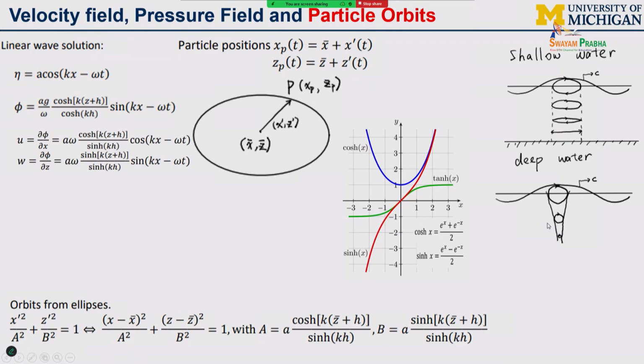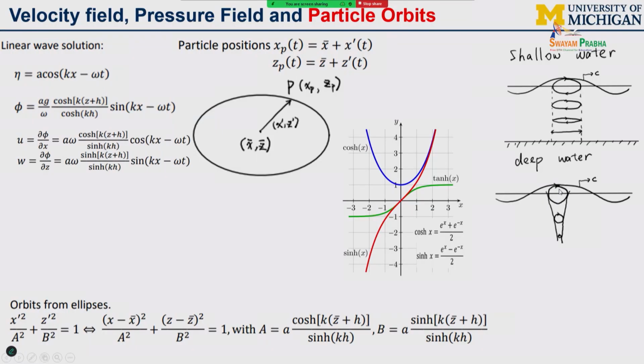Okay, when we say 5%, 23%, it means, okay, this particle motion, and at the surface, let us say the circle area, this amplitude is 1. At quarter wavelength, this amplitude decreases to 0.2523, and at half wavelength, this amplitude decreases to 0.05, right? This says the amplitude will quickly decrease.